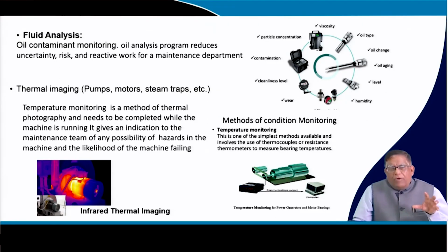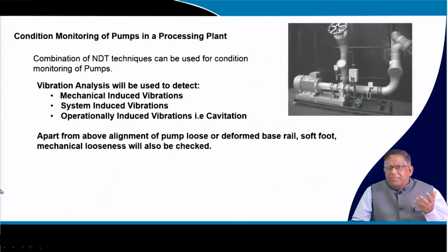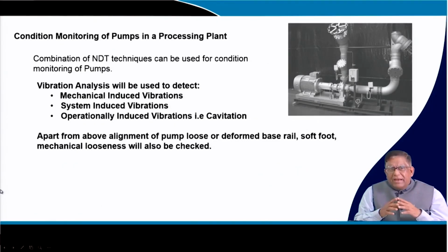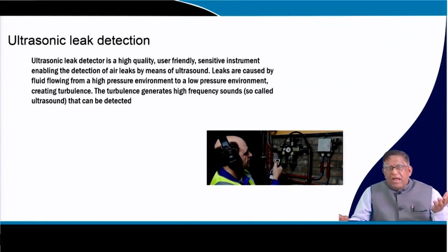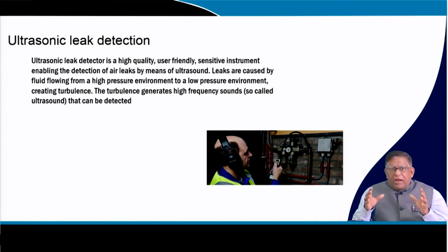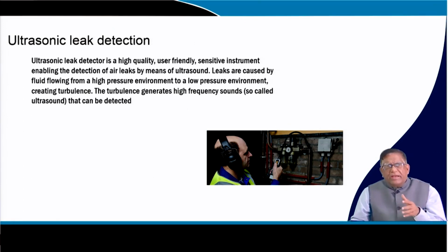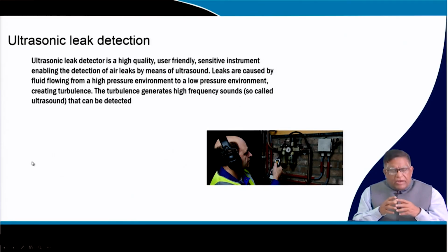That is how thermography works, with infrared cameras and infrared sensors taking the total thermal image of the machines. Similarly, you should study how different pumps are used in a mineral beneficiation plant and how the conveyor belts are doing. Many times in a pneumatic conveying or hydraulic circuit, if there is any leakage, you can use an ultrasonic leak detector.